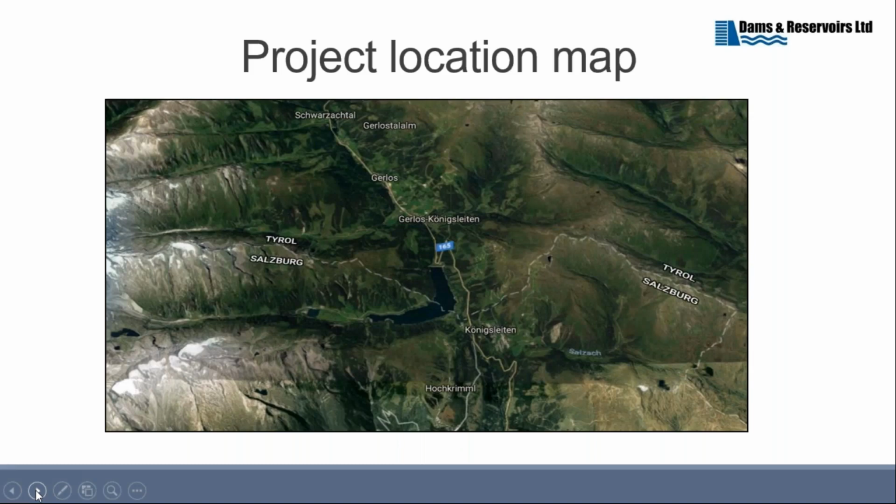So that's the warning about risk assessment, really, that you just have to be aware all the way through the process of where your levels of uncertainty are. And in 2002, I dealt with an emergency, which was some form of internal erosion. At the time we did the portfolio risk assessment of about 160 dams, the dam in question was number 22.